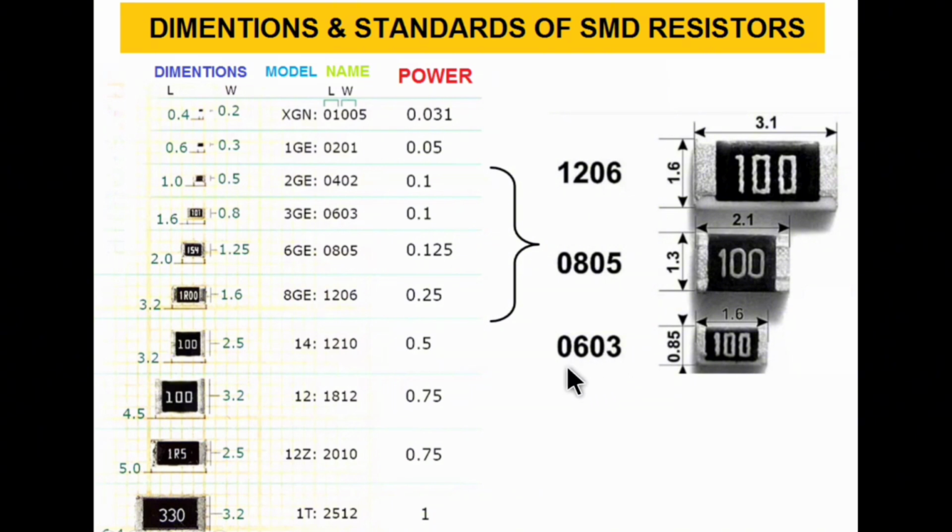But the ones that are very famous and practical are mostly 1206 and 0805, which can be assembled by hand, but the lower ranges are difficult. Well, there is a question of their power. For example, a resistor of 1206 has 1/4 or 1/8 of a watt of power.